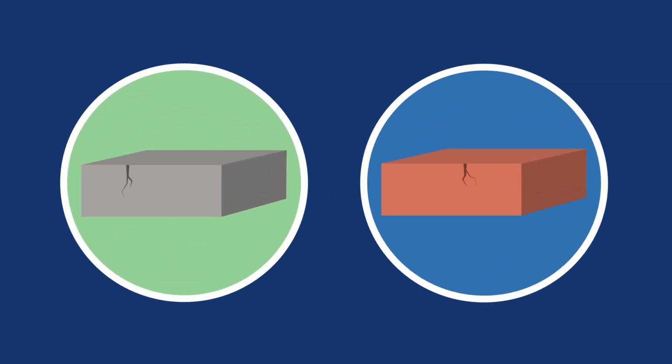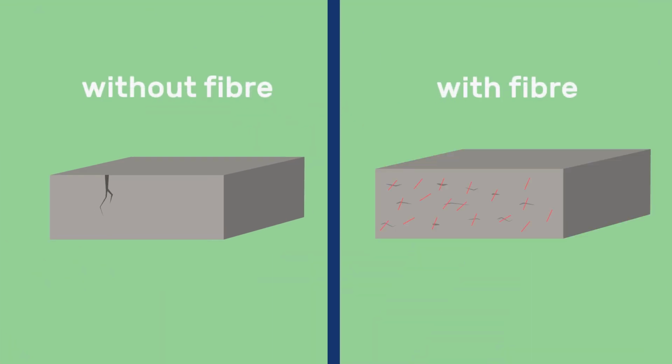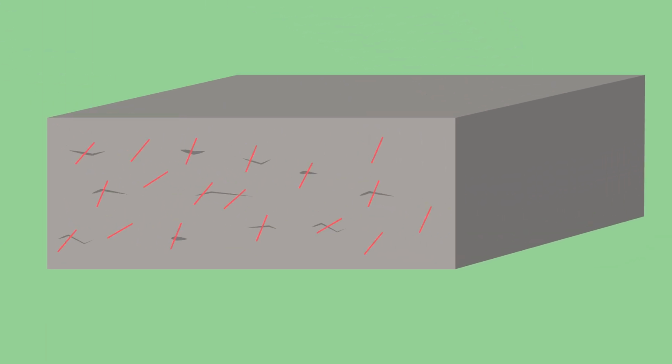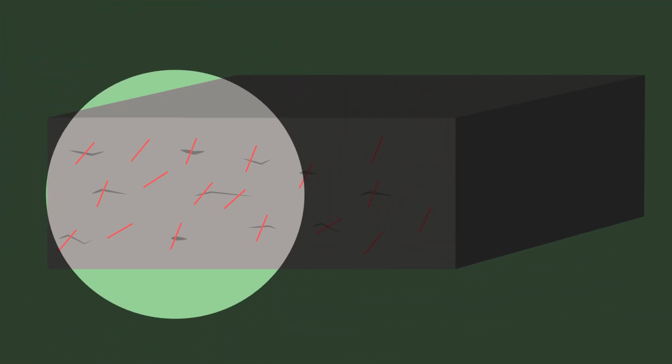The cracking risk of cementitious and earthen materials may also be addressed by adding fine fibers to inhibit crack growth. The initial drying stresses remain the same, but the material can resist these better. Overall, this mainly leads to more numerous and better distributed cracks that can be well bridged by added fibers.